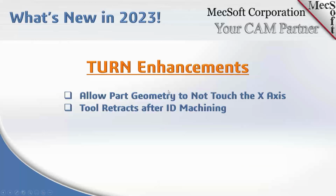Now we also made some enhancements to our turn module. Previously, we were limited in that when you created your geometry for your turn part, the geometry had to lie on the X-axis and touch the Z-axis. And that really caused some problems when you're parting off on the back of the part.